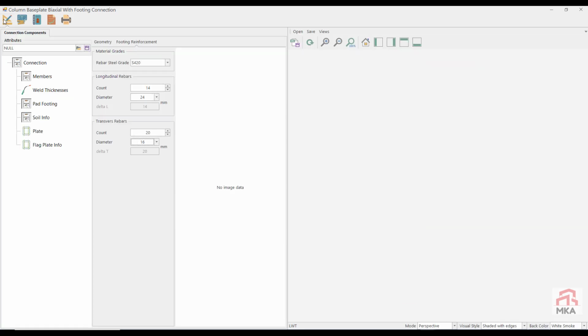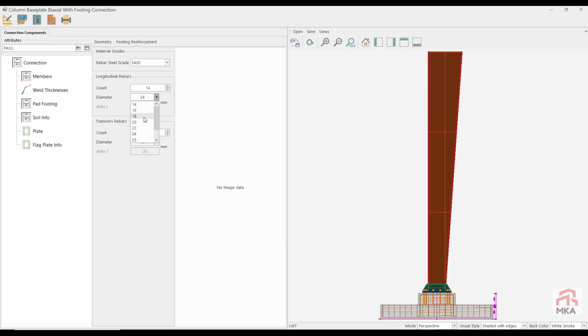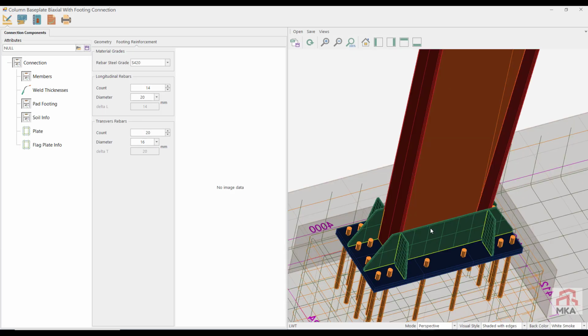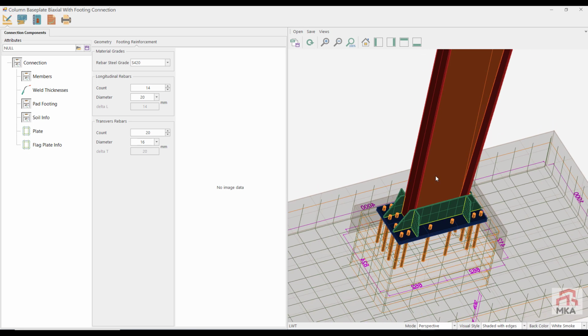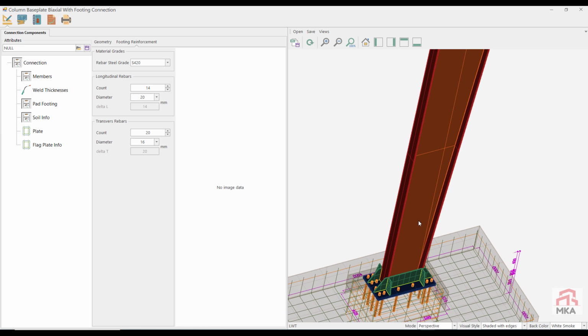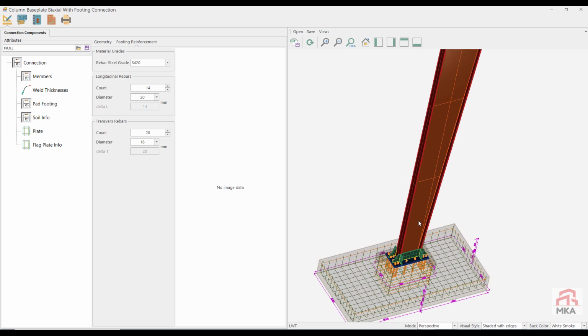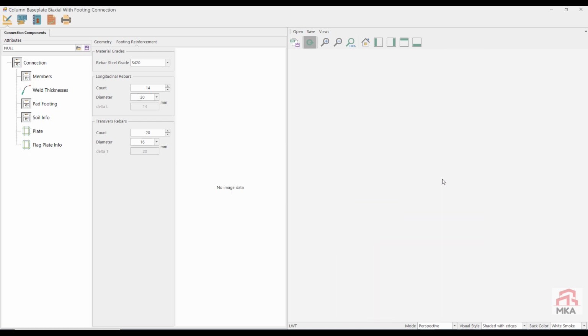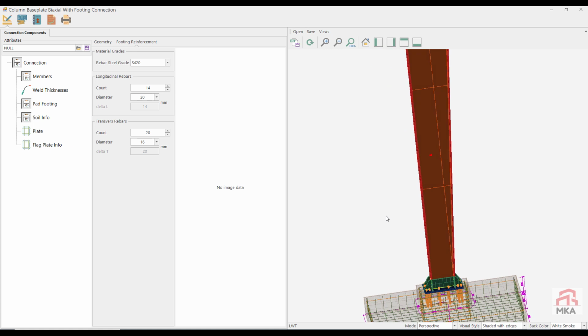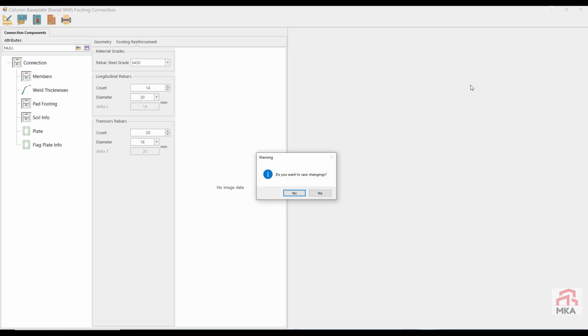There is a connection like this with 97% capacity. It is a bit unusual, but since the building is also unusual, this is only possible with such a column base plate. If we had made the base plate connection of the column with the foundation as a simple support here, maybe our column base plate would not have been this big and our pad foundations would have been smaller. But this time our column and rafter sections could have grown. I haven't tried it yet.